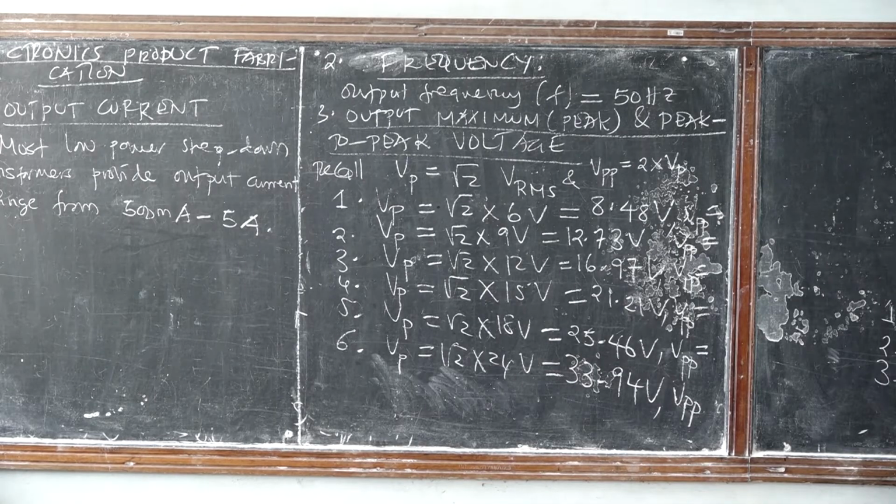If, for instance, the total amount of current that will be consumed by all of your system is 2 ampere, and then you choose a step-down transformer of 12 volts providing a root mean square current of 1 ampere, then your linear power supply will fail to power your system, because your system needs a large amount of current that the transformer cannot provide. Are we together?